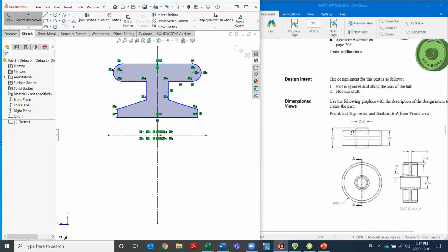So I might start on this top view, and I'm going to add these dimensions. And I'm just going to go down until I have all the dimensions added in. And hopefully that gives me a fully defined sketch. That's kind of the ultimate goal of our sketches. So looking at the top here, and remember, this view is this section down here. So it's also the side here.